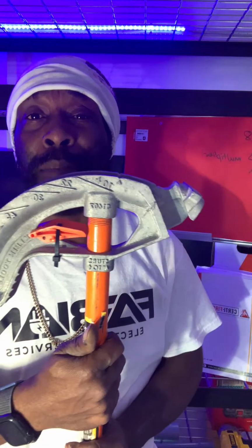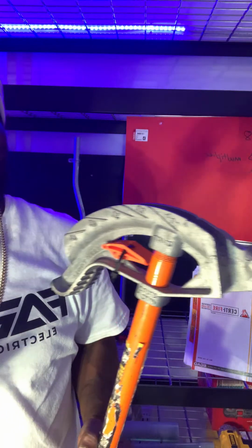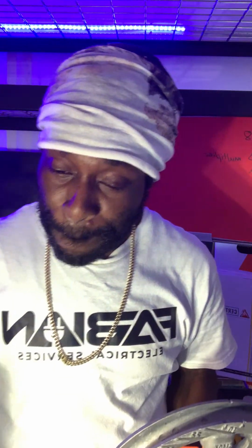What you're trying to do is avoid the unnecessary turning, losing conduit, scrapping conduit, throwing your conduit in the scrap, as we all are aware that once you start to throw your conduit away, it's wasted material. So to avoid that, using the star on a back-to-back 90 can be achieved. You just have to know how to go about it.